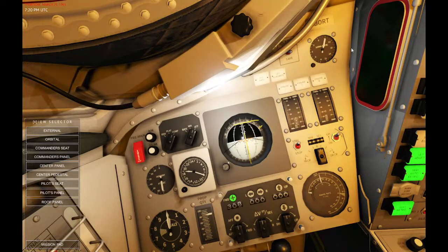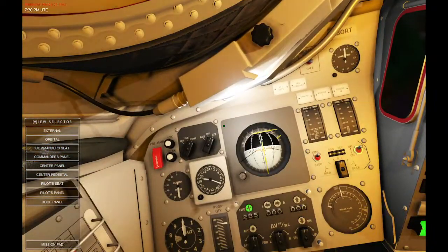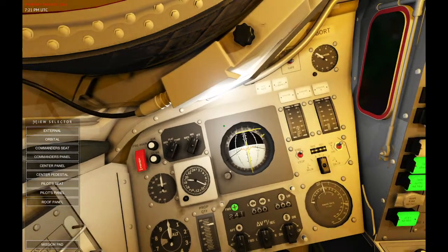Might have done a little bit too aggressive there. I should have started rolling up sooner. Alright, but we don't want to get too... Actually, yeah, we can float it a little bit. We've got 200 miles to go, and we're already slowing down significantly. So let's keep floating it. Yeah, should have started the roll upside down at around 3 degrees instead of 6. But at least I didn't go all the way to 15 this time. I am learning.